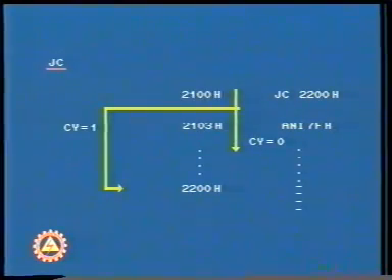At 2100 address, the program has a JC 2200 instruction. On decoding this instruction, the microprocessor will check the carry flag, and if it is set, then the control is shifted to 2200. Otherwise, if carry flag is reset, the control continues sequentially. Let's study a problem having both conditional and unconditional jump instructions.